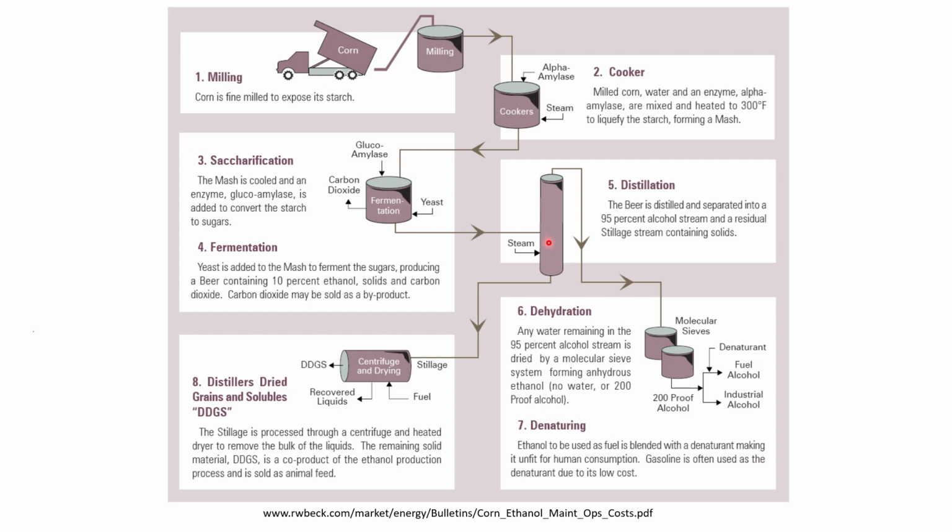What's left over, what comes out the bottom of the distillation column, so we've taken the product from the fermenter, sent it to the distillation column, and ethanol went out the top. What comes out the bottom, what's left over, is called the stillage. And this contains all the solids, primarily the yeast and other insoluble components of the corn kernel. This is referred to as the stillage.